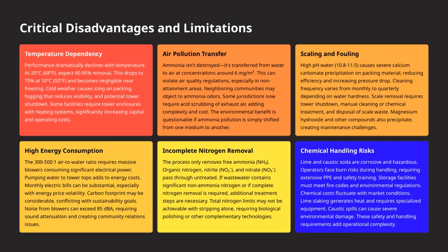almost negligible. Cold weather also causes icing on the packing, fogging that reduces visibility, and even potential tower shutdowns. Some facilities need to enclose the towers and include heating systems, which can greatly increase both capital and operating costs.